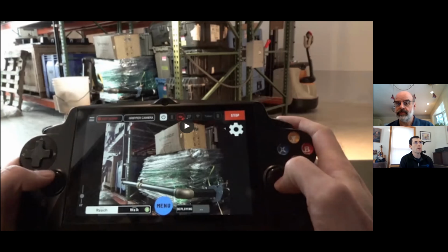We have a question about the payload here. Can we add a payload to the head of the ARM and communicate via Ethernet to the internal network of SPOT? In short, can it be treated as an external payload interface? Yeah, the form factor of that interface is a little bit different, but yes, functionally it's the same interface as you get through the DB25s, except I guess we don't have the emergency stop power disable feature on the gripper.